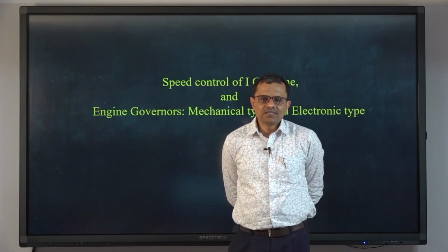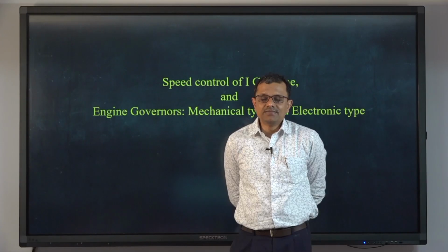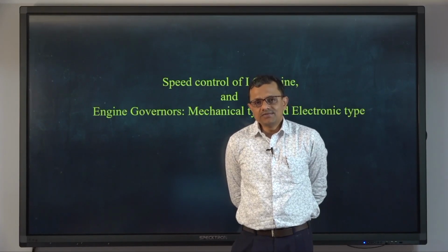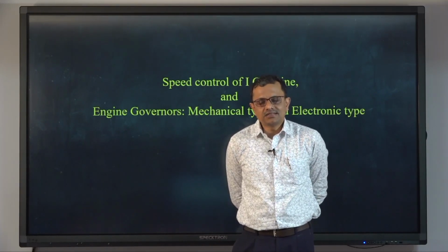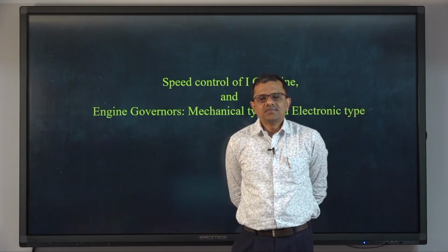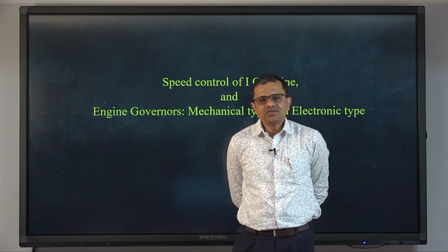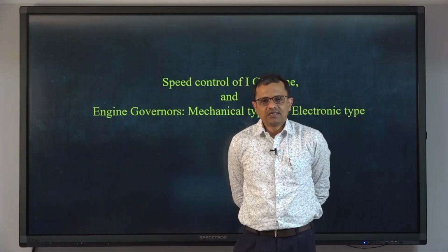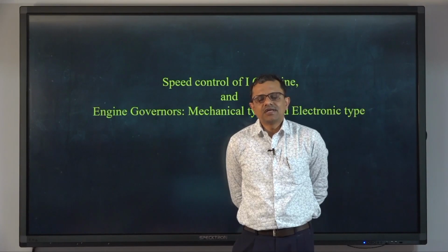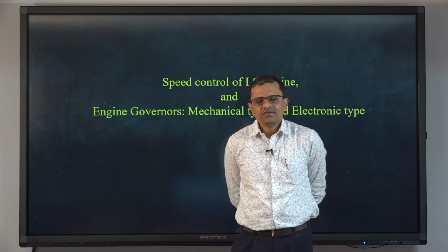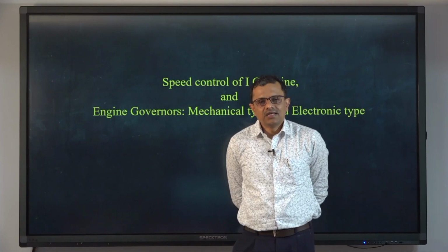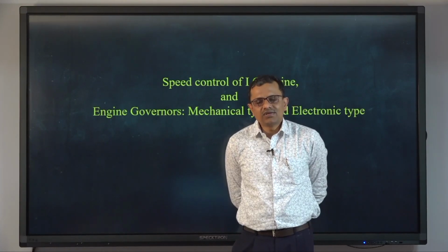Now, we have seen that the electronic control unit or engine management system, upon receiving feedback from these sensors, does some task essentially to control a few parameters, and what are those parameters? Say, for example, spark timing, fuel injection timing, fuel flow rate, exhaust gas recirculation rate.